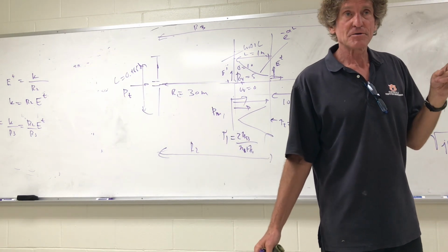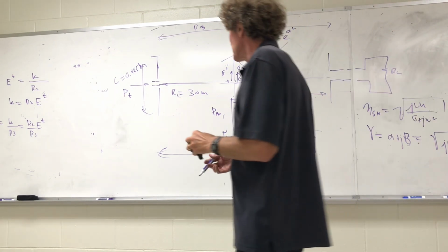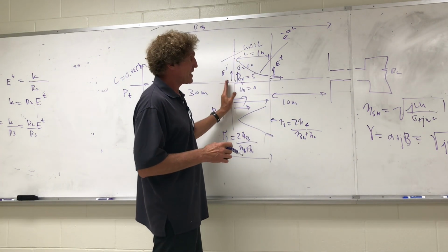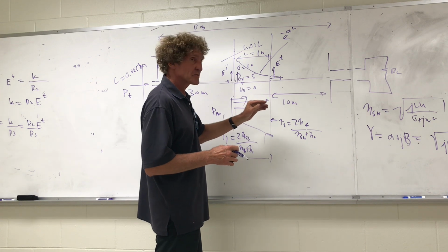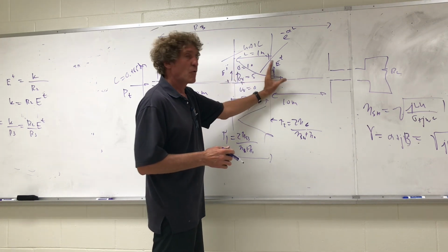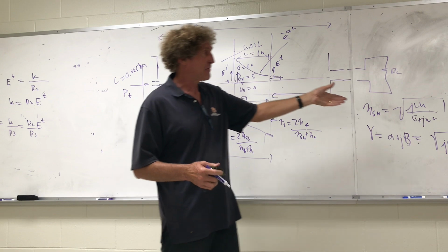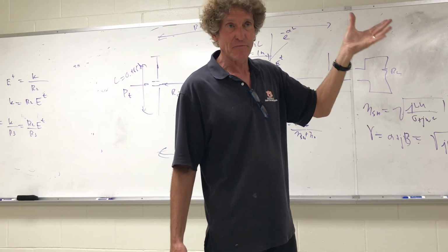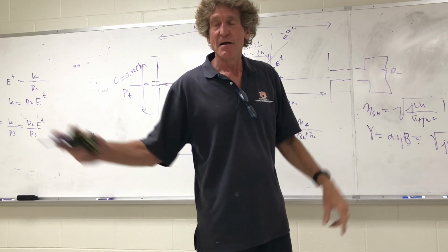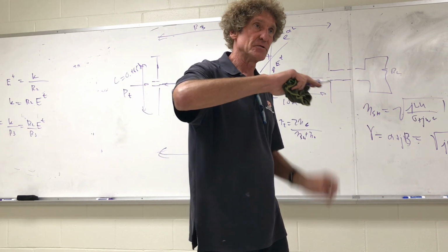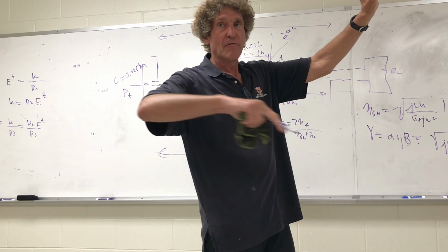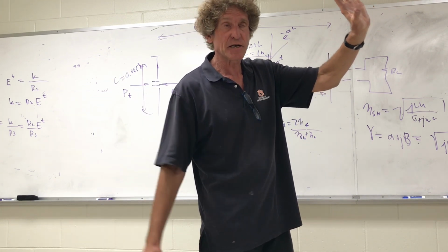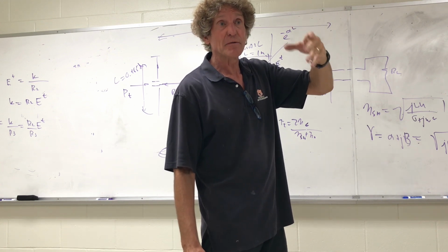And what I want you to do, if you did this, is you want to see something about, say you get curves, you want to find out if you're exactly 10 meters away, maybe how thick this wall could be before you get a voltage level below, like 20 nanovolts or 20 microvolts. You all follow me? You set some parameters, then you have to model it and you'll get curves. You'll say voltage on load versus frequency, or voltage on load for a given frequency versus thickness. And you get what are called family of curves.